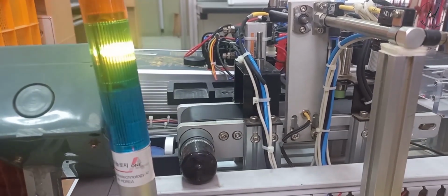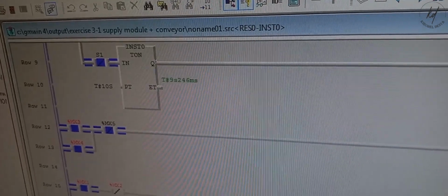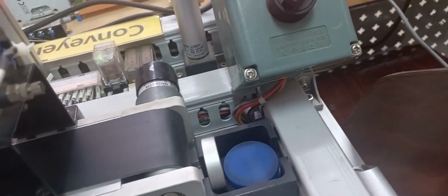In row 8 a branch ladder logic is formed with the sensor's input, so if there is no object interference inside the supply box, that would trigger the input pin of an on timer, so that it waits exactly 10 seconds and stops the overall process. Or if any object is inserted in the supply box between the prescribed times, that automatically goes to trigger the solenoid valve.